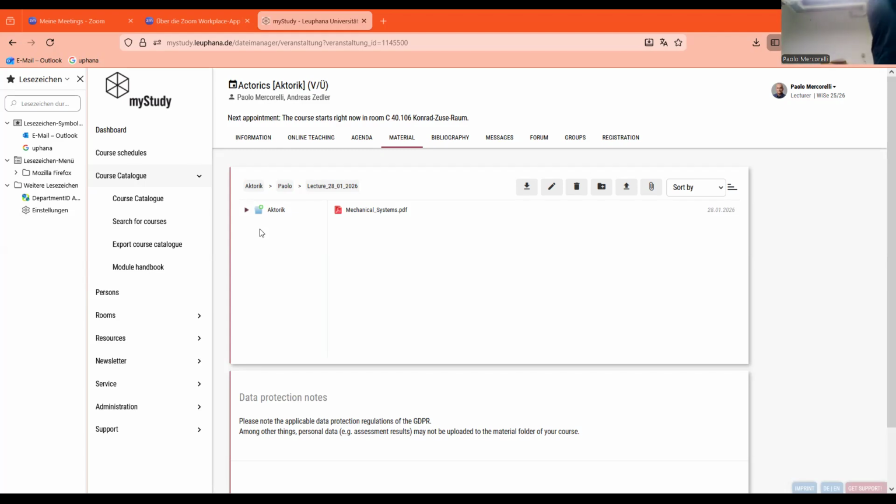Why that? Because in robotics, if you have many arms, many legs, this is complicated. And this matrix, this inertial matrix, depends also on the position of the mass. It's not exactly the mass, it's the inertial matrix. I mean, in this position here, I have an inertia which is different. Here, we can understand, I have to put more effort to stay in this position. This means this inertia depends on this angular position. Just intuitive.